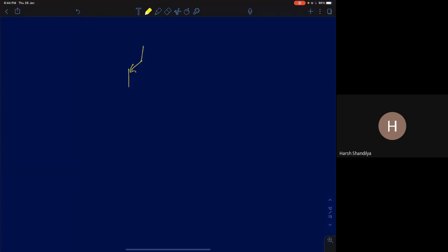So let's say we have a PNP transistor. Now, how do you plot the IC versus VCE of a PNP transistor? So this is your VBE for a PNP, right? If I want to bias this PNP with a voltage of VBE, let me write it, this voltage is mod VBEQ. That is your base emitter voltage. This is a PNP transistor, so then this node voltage will be VCC minus mod VBEQ. That will be this node voltage here.